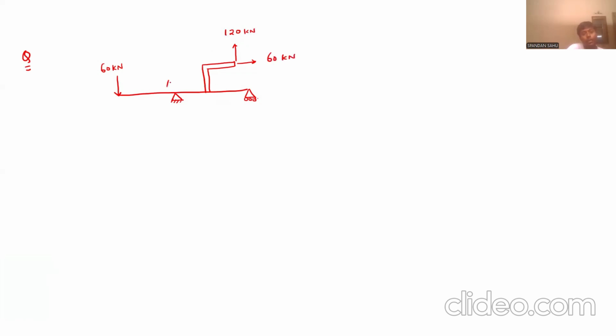So this point is point A, B, C, and D. Now they are asking what will be the reactions at supports. So how to calculate? First, take this L-shaped bar out and draw its free body diagram.